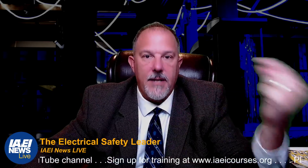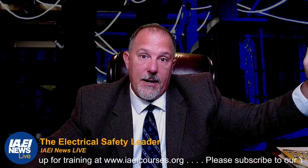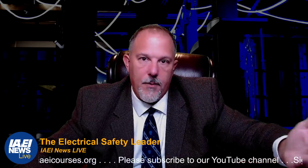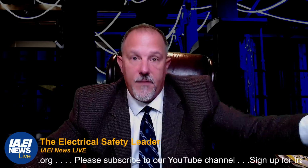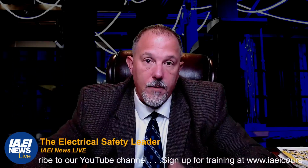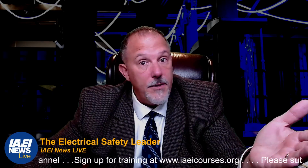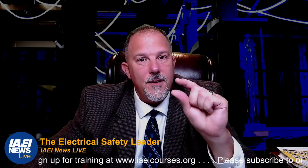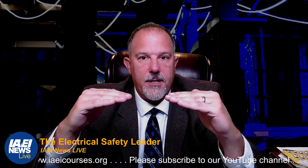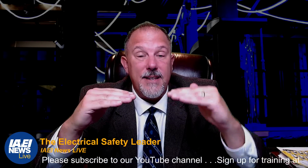Then you pick the overcurrent protective device. And the overcurrent protective device can be one step higher than the standard. If it's 125 and you can't buy a 125 amp breaker, you can buy 150. You can put 150 on it because it's the next standard breaker. And so as long as you meet the other rules, right? But in any case, the conductor has to carry the current continuously. So your 100 amps of load current, where you could have used 100 amps worth of conductor, now you're going to use 125 amps worth of conductor. So you're increasing the conductor size.